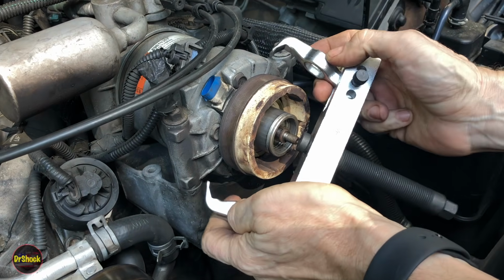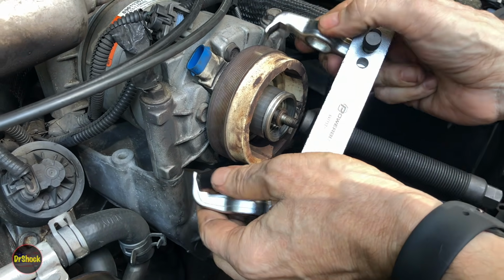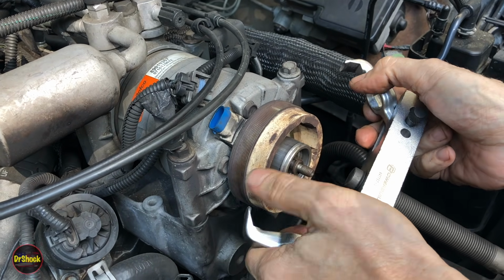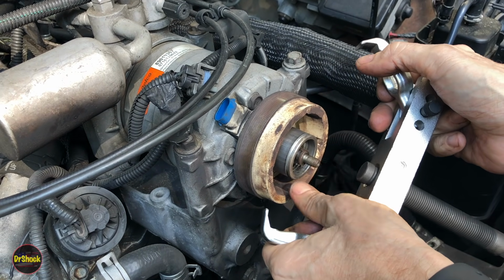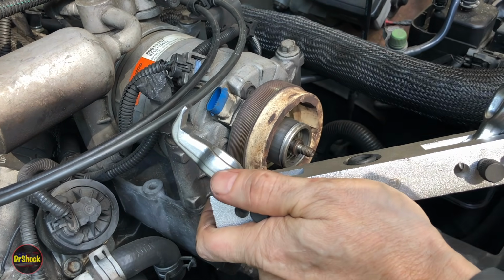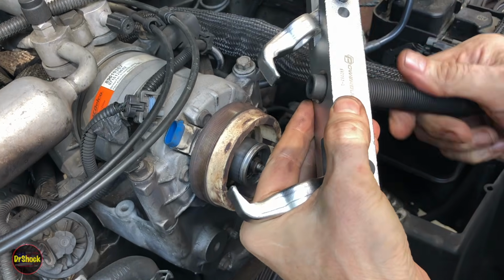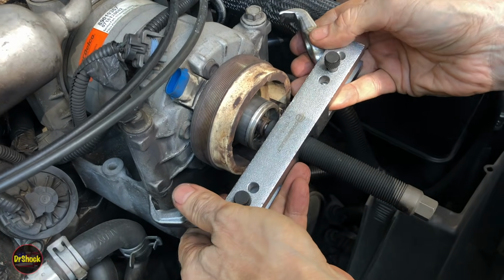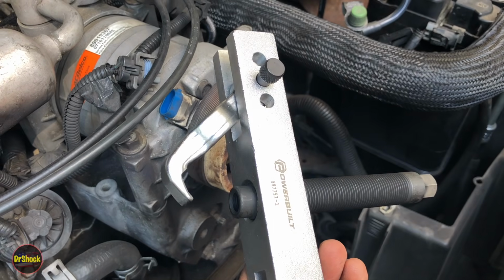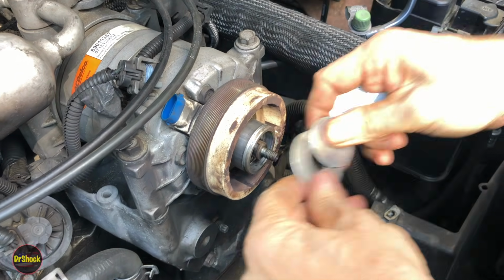All right, guys, the problem with our puller is we've got an arm that'll fit behind this electromagnetic coil, but the arm's too short to get the cross piece in. And I also still want to get the pilot in there, but I can't. So I'm going to show you what I'm going to try. I'm going to try taking a plunger out of this, because the shaft will fit right onto there. But I still want to not hit the shaft, so I'm going to try a little improvisation here.